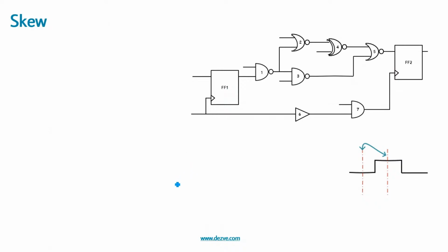Now what we are trying to say is, what happens when the skew occurs, correct? Now let us see the hold. Data required time minus data arrival time should be greater than or equal to T setup. Data arrival time minus data required time should be greater than or equal to T hold, correct? Now in case of setup, for our analysis purpose, we want to increase this. So this is max and this is min, correct? And for hold, we are trying to increase this. So this is max and this is min, correct?